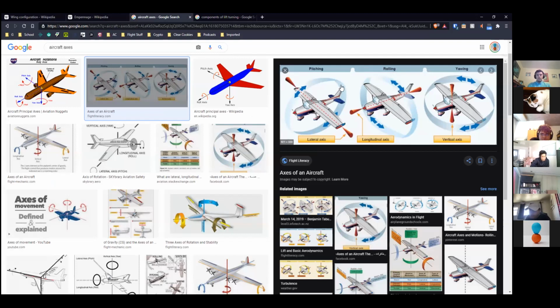Your ailerons and rudder are still important, but there's a lot more leeway in how you design them. Whereas we call this the horizontal stabilizer, the thing that the elevator is attached to, but sometimes you just call the whole thing that, the size of that will directly affect if your plane flies correctly and how easy it is to control. So that becomes really important.